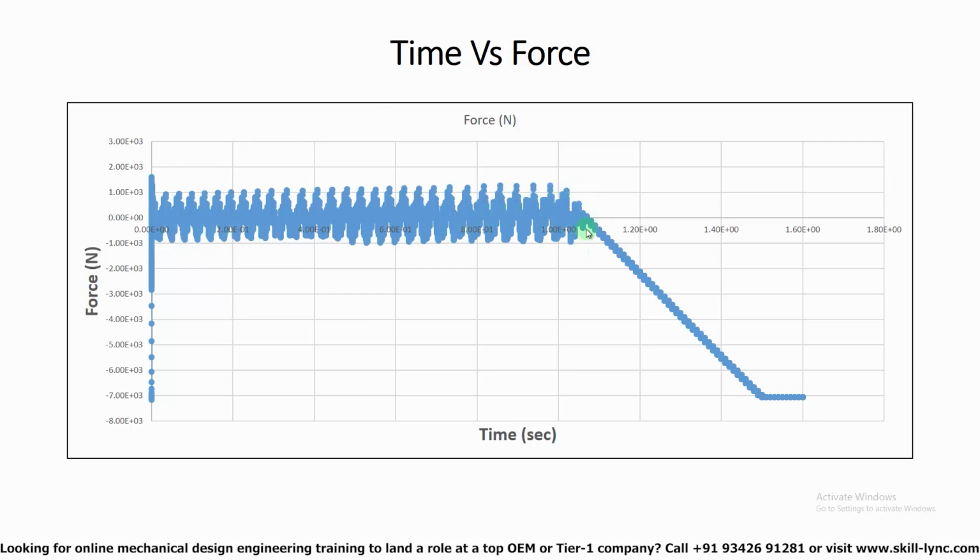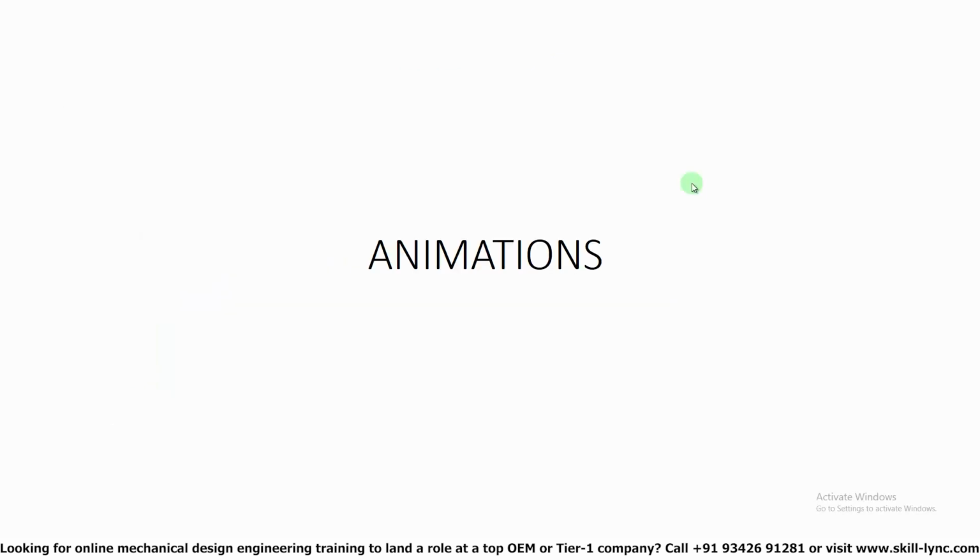And here you can see that after the inlet pressure line restores to its original value, the force again goes back to its baseline values. So this tells us that the simulation is behaving properly. Now let's take a look at a simple velocity animation.